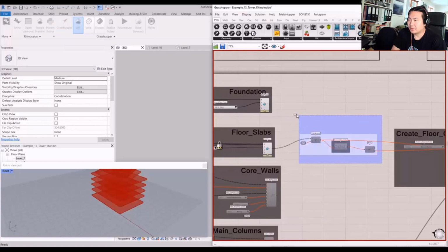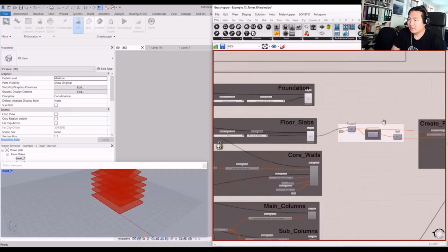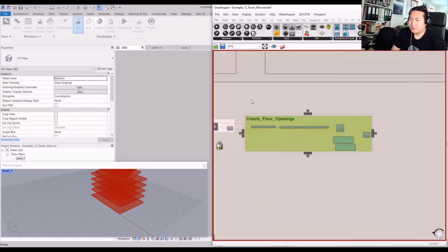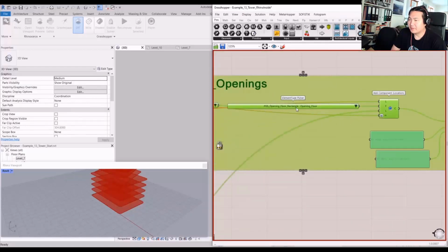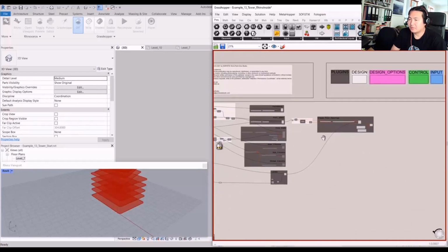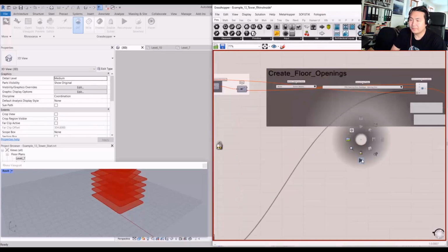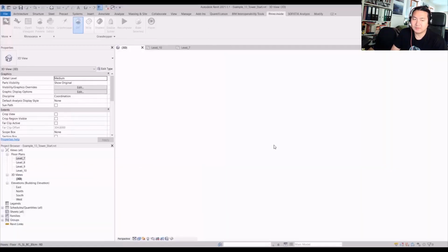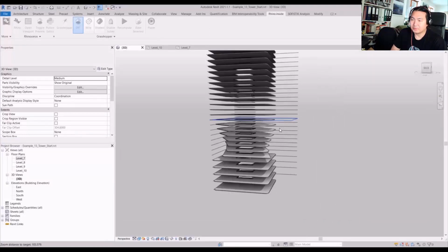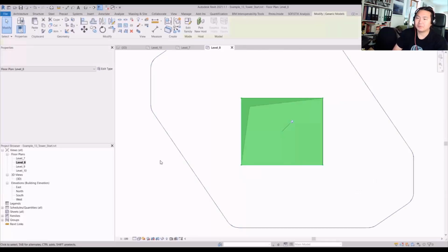Now we just organize the tree structure, the Grasshopper tree structure, and find out the center point of the slab, and we can insert openings, and also the spatial family is inserted, and that parameter is also adjusted through the Rhino Inside script. So when I now recompute, you can see all the openings are going to be inserted. Yeah, it's beautiful. So we can see the shaft openings are applied, and in the plan you can see the symbol directly.